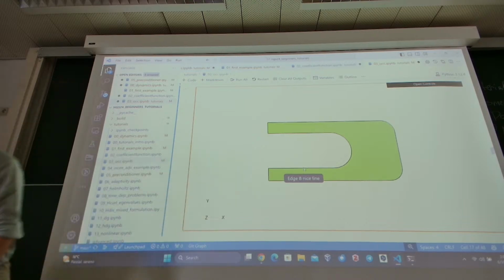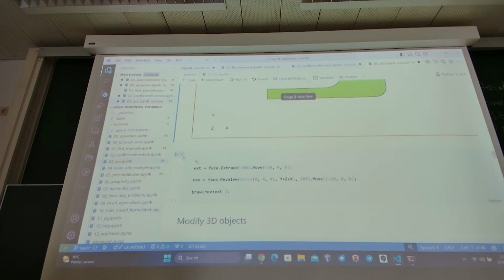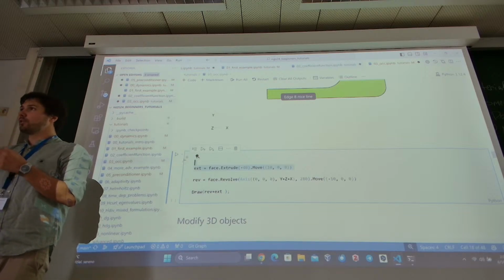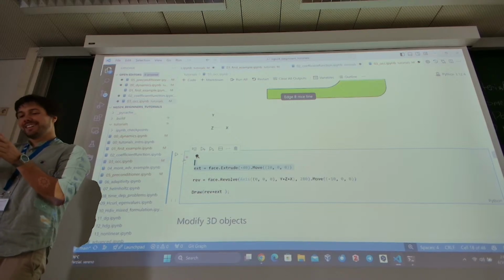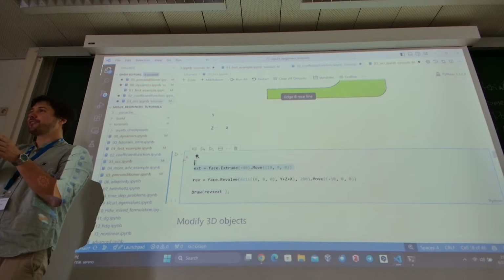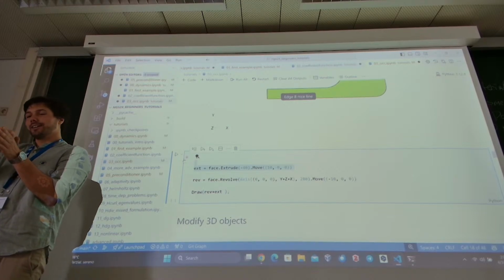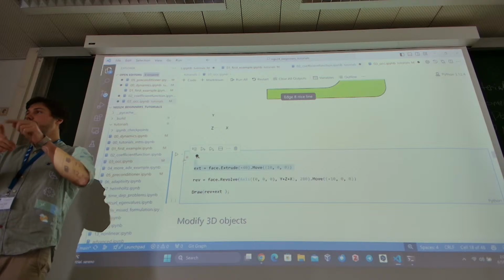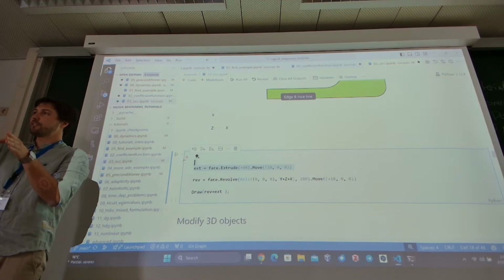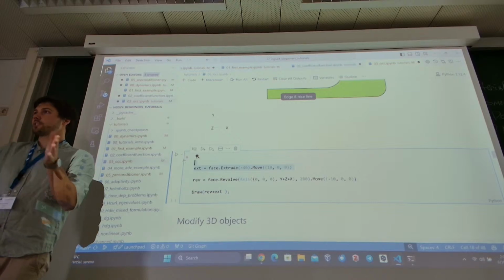Okay, why should we define names in 2D when we are creating objects in 3D? Well, when we extrude an object, or we rotate or revolve an object, we create a 3D object from a 2D one, based on, let's say, the hierarchy of the image. It will somehow spread the names that you predefine. So if you define the name on the line, and then you extrude the line, then the surface will have the same name. The same thing is going to happen for surfaces and volumes.